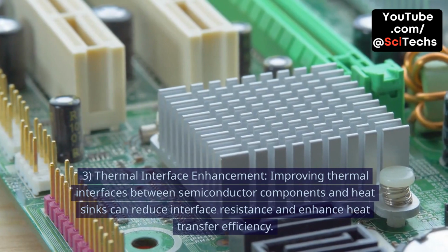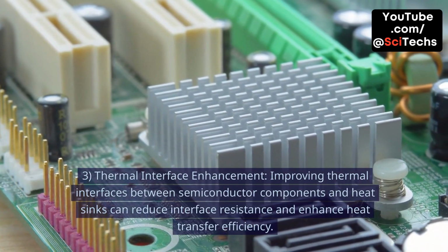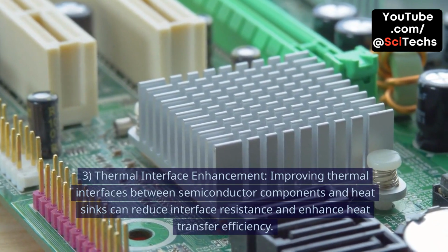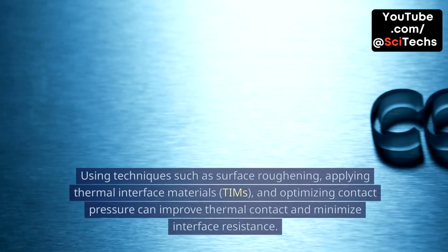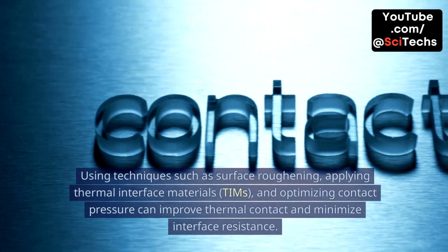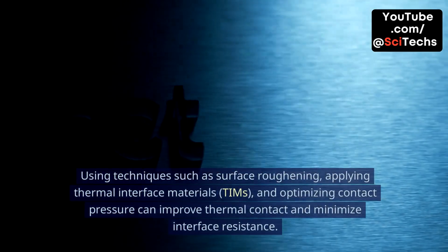3. Thermal interface enhancement. Improving thermal interfaces between semiconductor components and heat sinks can reduce interface resistance and enhance heat transfer efficiency. Using techniques such as surface roughening, applying thermal interface materials, TIMs, and optimizing contact pressure can improve thermal contact and minimize interface resistance.